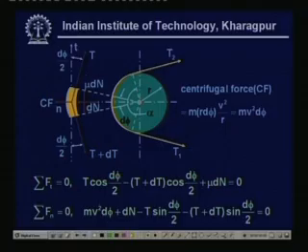This is the belt and a segment of the belt is this one, this yellow color is the segment of the belt, and let this segment of the belt subtend an angle d phi at the center. So, the length of this particular belt will obviously come out to be r d phi. Now, let us see what the forces are that act onto this small belt segment.